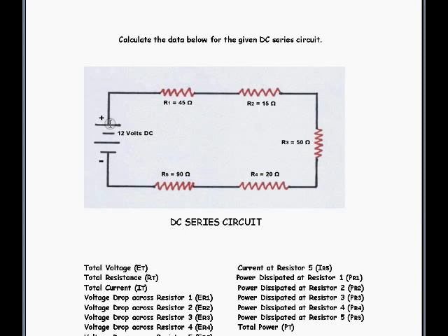So once we calculate the total current, we can use the fact that series electrical circuits maintain constant current. So whatever our total resistance becomes from that formulation, we can then solve for the voltage drops.